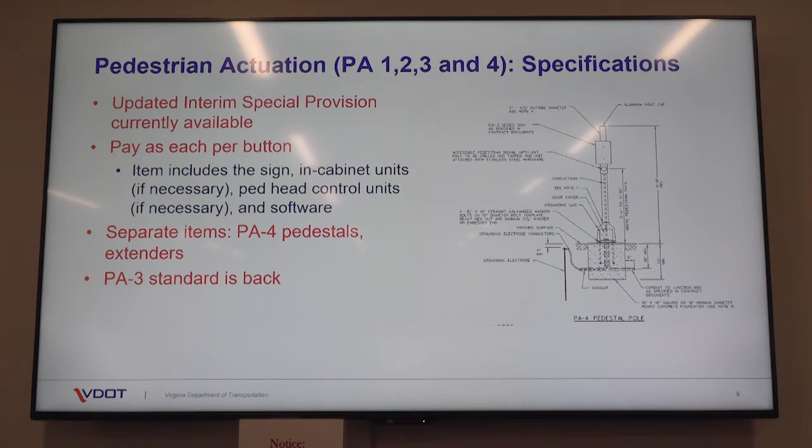So now the push button needs to be less than a foot? Yes, the push button needs to be less than a foot, but the foundation of the PF2 can be installed flush with the sidewalk to not create that barrier. But the pole is not supposed to be within a foot, right? The PF2 pole can be directly adjacent to the sidewalk with the new standard update.